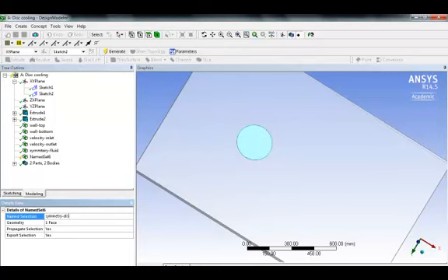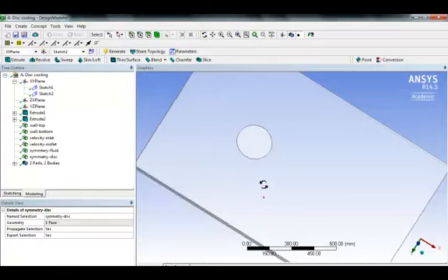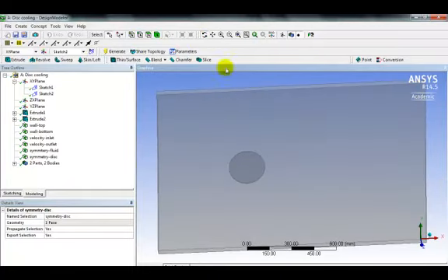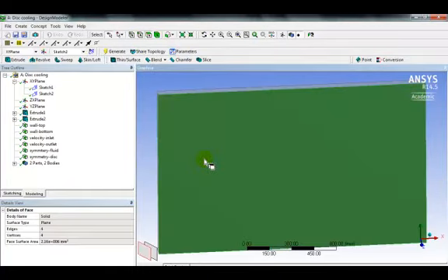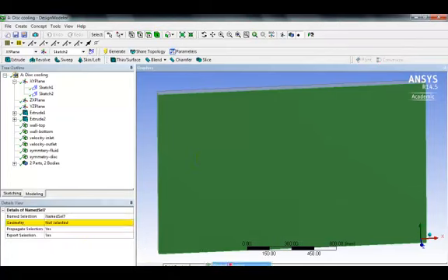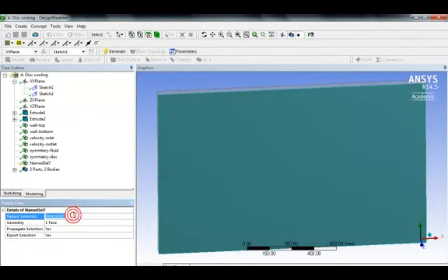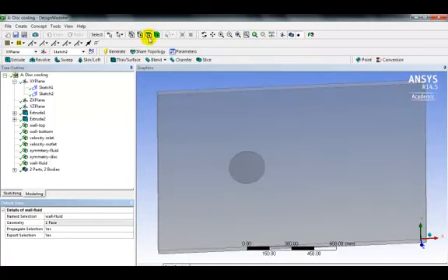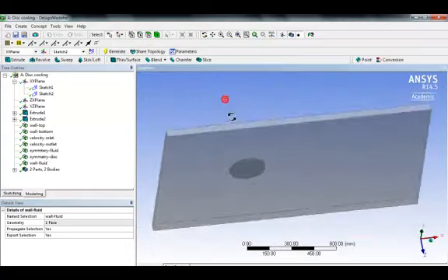Symmetry disk. By calling it symmetry, Fluent will automatically make it the symmetry wall. And then we need this big wall here. Name section, apply. We'll call that wall fluid. Generate. So we've named the entire exterior.